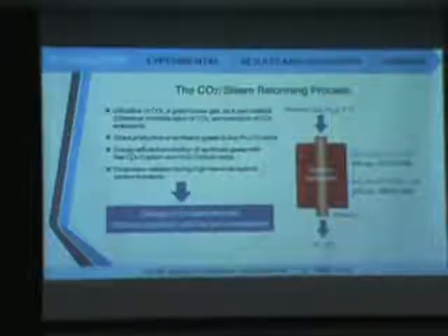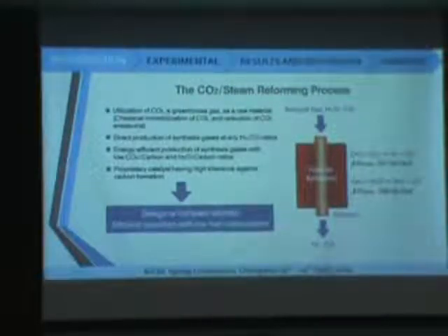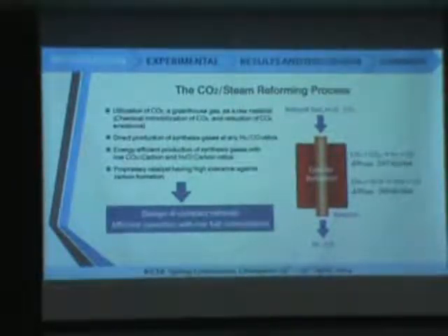And for the reforming process, nowadays we have two types of process. One is called the steam reforming process. In this process, they add natural gas, carbon dioxide, and also water for this reaction, and the ratio of hydrogen and CO depends on the process, between 1:1 or 3:1.